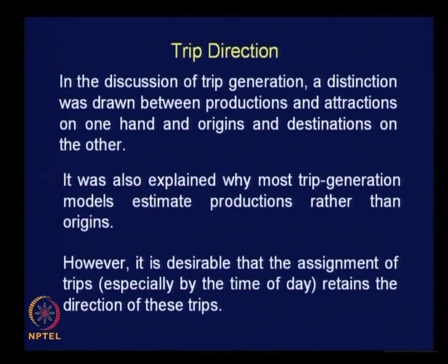However, it is desirable that assignment of trips, especially by the time of day, retains the direction of these trips. It is obvious, that is what we discussed about. While you assign traffic, the direction of movement has to be retained, which is possible by converting your PA matrix into OD matrix. That is why we discussed conversion of PA matrix into OD matrix only for this particular purpose.